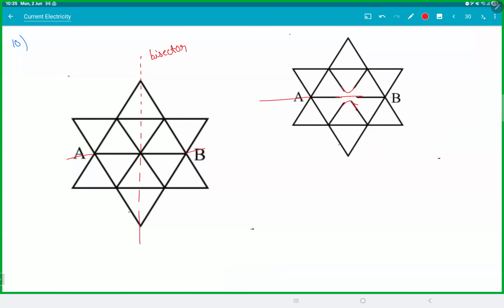Now I can actually fold this, but I can get it even faster anyway. If you see, this entire triangle is R, R, 2R, and this is R, 2R by 3. Agreed? Parallel. This triangle is also 2R by 3. These two are 2R, these two are 2R, 2R, 2R is R, R, and the middle one is a resistor. So this whole section is R by 2. So the top three are in series again. So yeah, you are done.